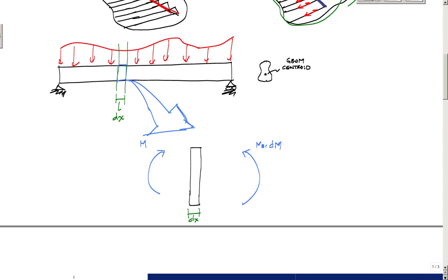And in fact, if you remember, if you make a cut and you look at the right side of the cut, you would say that the shear goes upwards over here, and on the left side of the cut you would say the shear force goes downwards over here. Okay, and it would be like V plus dV or something like that. All right, but that's not so important. Let me erase that. I don't need that right now because I want to draw the normal stress profile here.